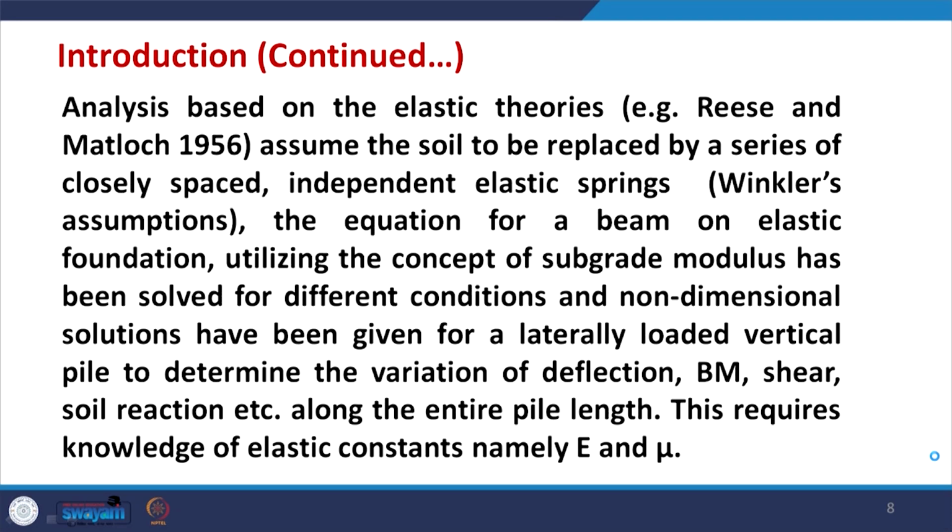The equation for a beam on elastic foundations, utilizing the concept of subgrade modulus, has been solved for different conditions, and non-dimensional solutions have been given for laterally loaded vertical piles to determine the variation of deflection, bending moment, shear force, soil reactions, etc. along the entire pile length. Calculating this requires knowledge of the elastic constants of the soil, which are Young's modulus E and Poisson's ratio.